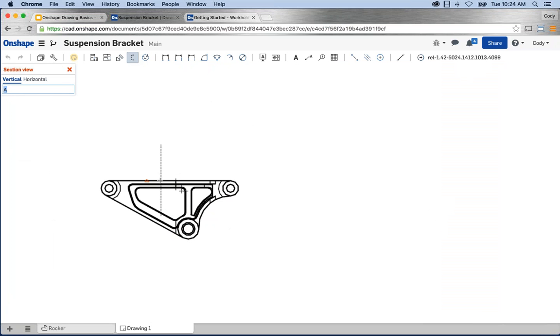And if you look really closely, you'll see these attachments are actually different shapes. So there's a square, that's a triangle, that's a circle. And so they give you visual feedback. For instance, the square is the end of an edge or an end of a line, where a triangle is the midpoint. A circle is a center point. So it's giving you visual feedback to what you're attaching this section view to.